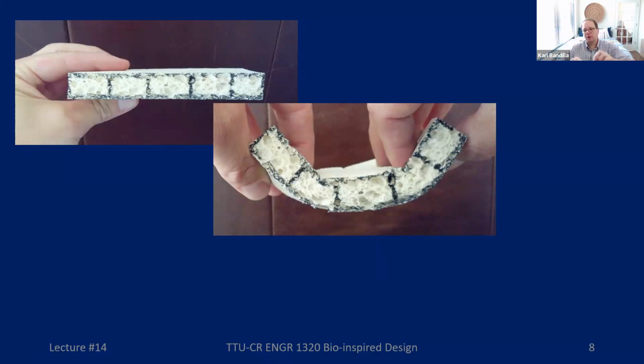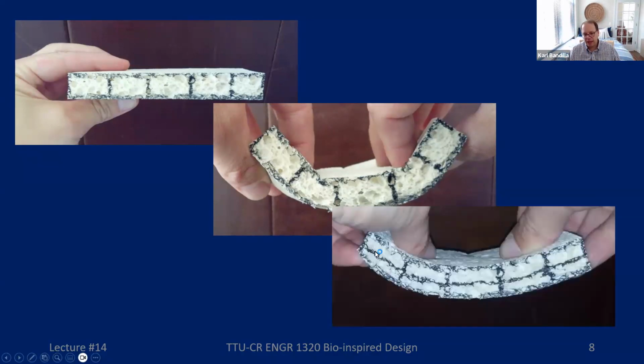And we talked about this already when we talked about the idea of concrete, right? That whenever I have a beam, it gets pushed very hard at the top and stretched at the bottom. However, if we look at the center of this, that doesn't really change very much. It's not being stretched, it's not being pushed. So there's not a whole lot of what we call stress in here, right?